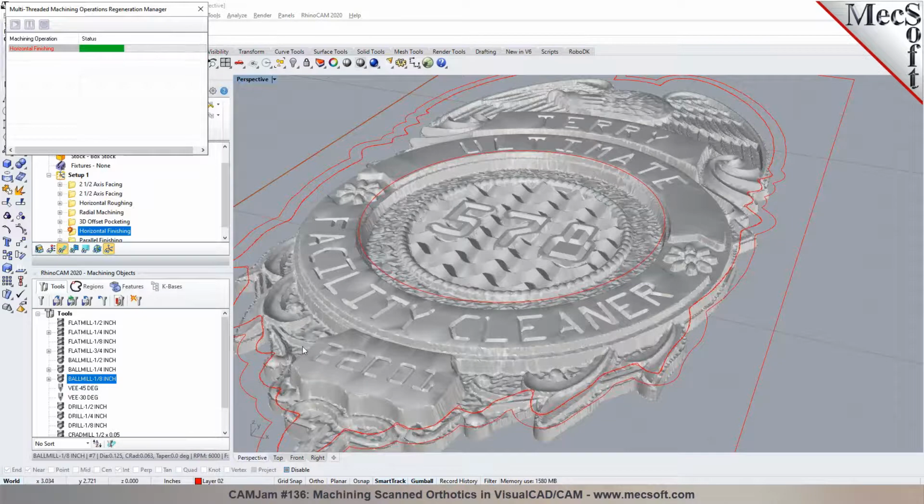Rather than just rastering back and forth, it's going to go around in constant levels. Some systems also call this waterline finishing or Z-level finishing. It maintains a constant Z for each cut level and then steps down in level. When you have steep sections on the part, this would be a good way to program it, like these sections with the steep sides. For steep sides, this will work very well. It's working through computing the toolpath, since there are several features on this model.